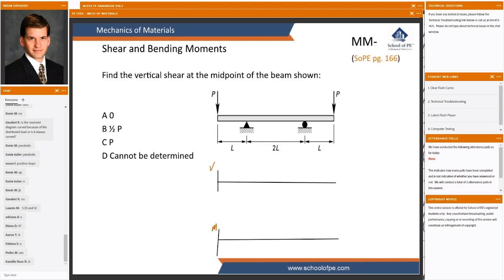All right, so we can take our original diagram and turn it into a free body diagram by scribbling all over it, as we often do. What's our shear diagram going to look like? Well, it's going to include a value of 0 and every value from there down to negative P. Is there any change in that diagram going to happen over this next little length?